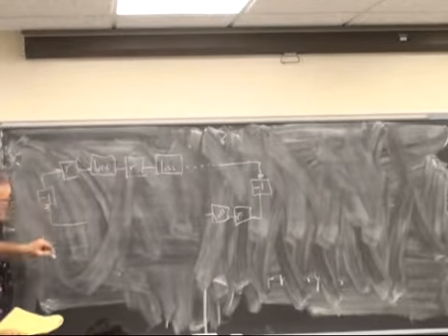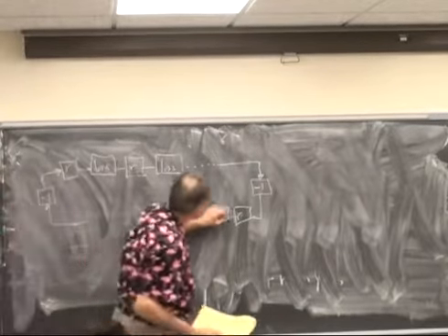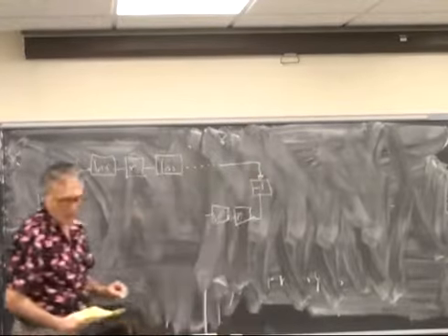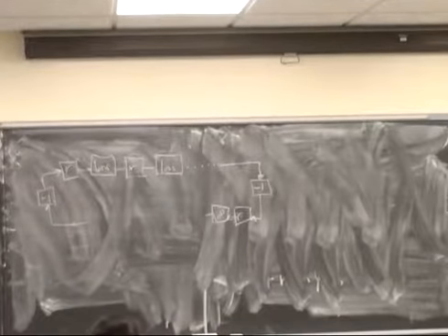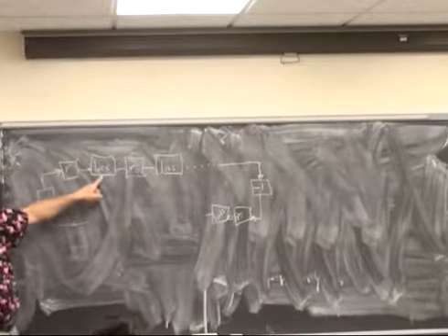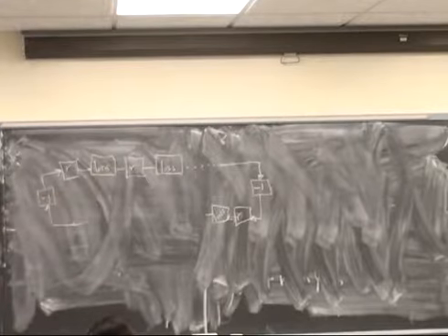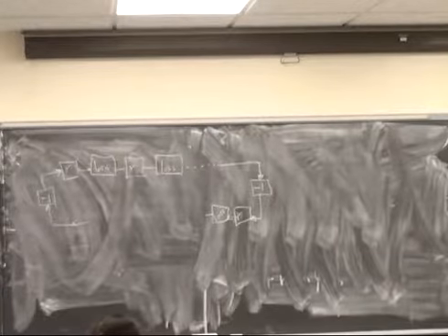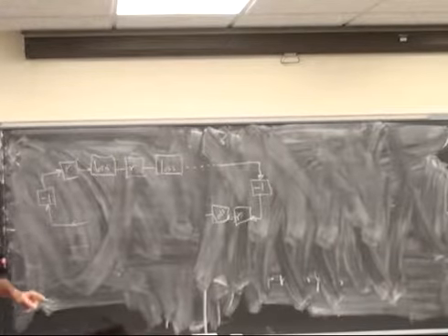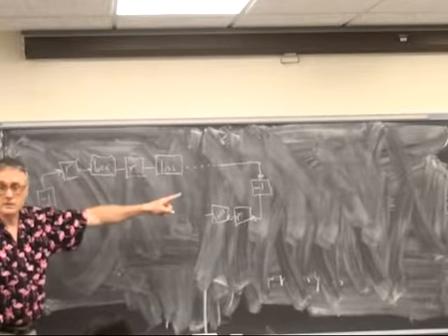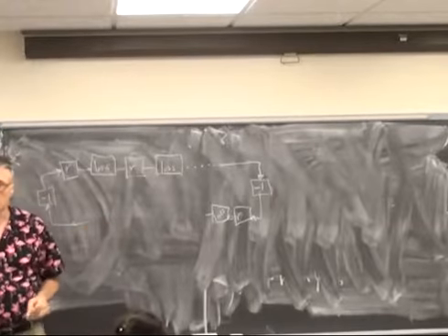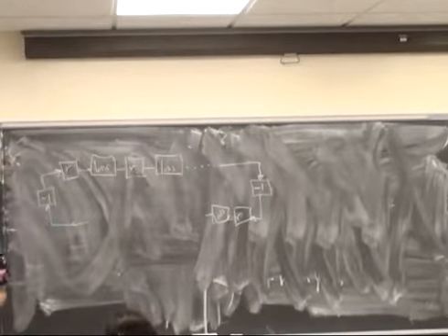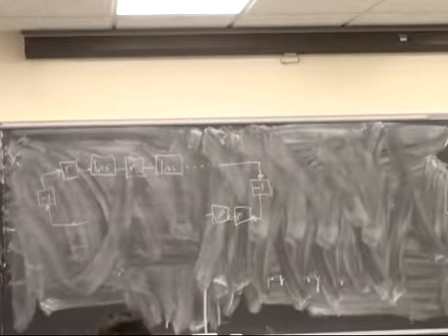So we can then notice the loss elements are all represented as a linear loss, which is to say you're multiplying by some attenuation coefficient, then multiplying the function by a series of losses throughout the loop, and multiplying by -1 twice can all be commuted into one gain.